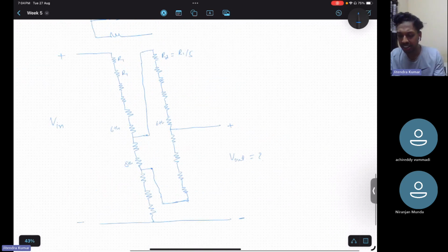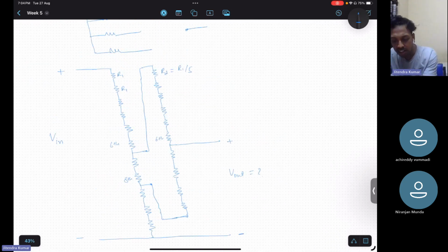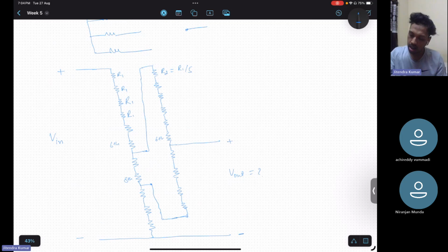So it will be nothing but a kind of voltage divider circuit. But how do you calculate this? It just looks intimidating, but it is not that intimidating if you simplify it. All these resistances are R1. So how do you solve it? Because you know the potential divider rule, or voltage division rule, and how to apply it. And it is nothing but the Kelvin-Varley potential divider.